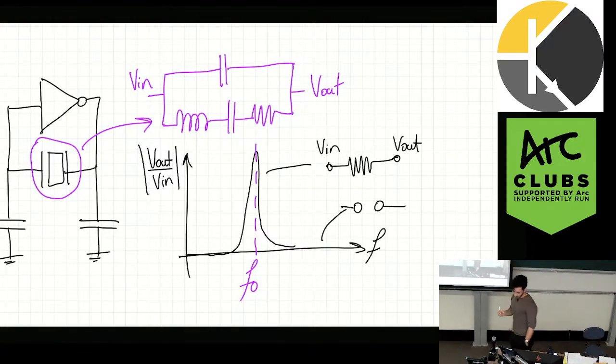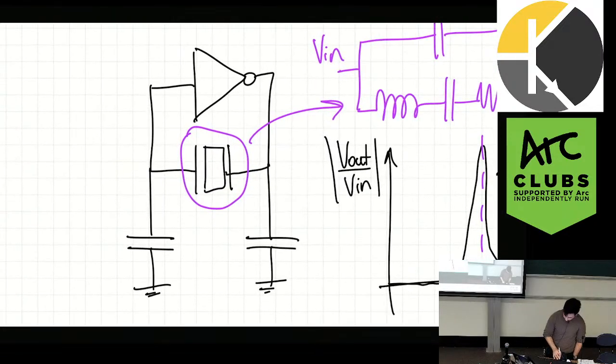Now, why this is important is because if I look back at my Pierce oscillator, what I can see is that the inverter loop is only ever going to have a feedback loop at what frequency? The resonance frequency. Because what happens outside the resonance frequency? What does this crystal look like outside of resonance? Open circuit. So is there going to be a feedback loop? No, right? So what we can see is that there's only ever going to be a feedback loop established at that one particular frequency, right? Which is how we get an extremely selective frequency. Does that make sense so far?